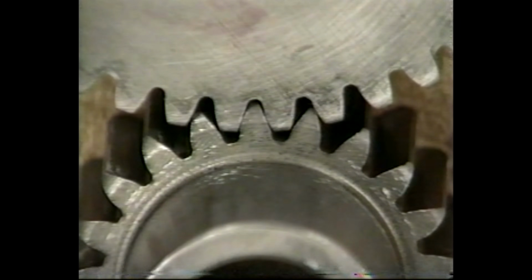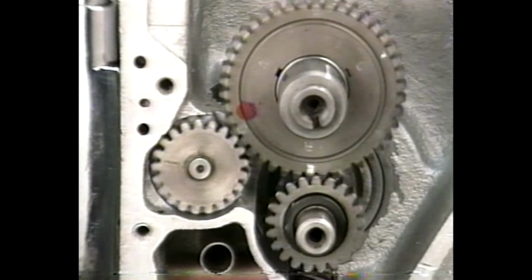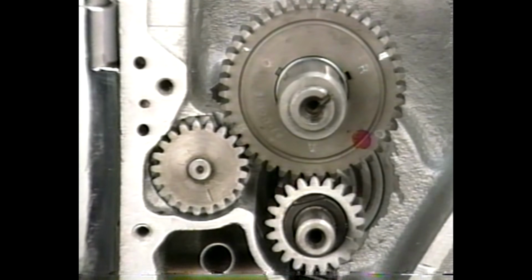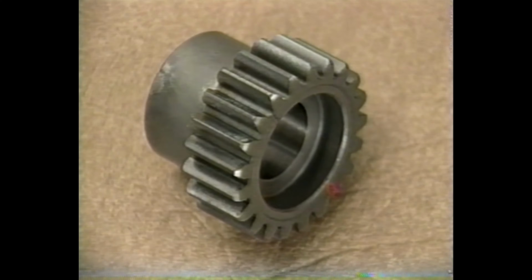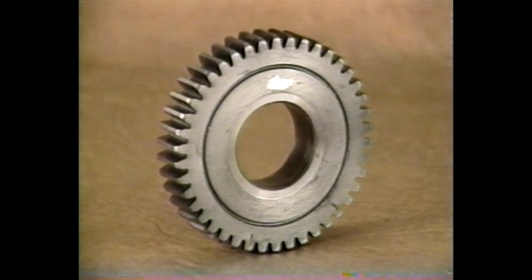A tight-fitting pinion shaft gear and a cam drive gear will result in both gears trying to climb one another, thereby producing a very noticeable howling or whining noise. This condition of tight-fitting cam drive and pinion gears must be remedied immediately. Otherwise, the two gears will quickly destroy each other's teeth and bearings, if allowed to operate for any length of time. To solve this problem of zero backlash, we must choose either a smaller pinion gear or a smaller cam drive gear to give us our minimum backlash of 0.002.